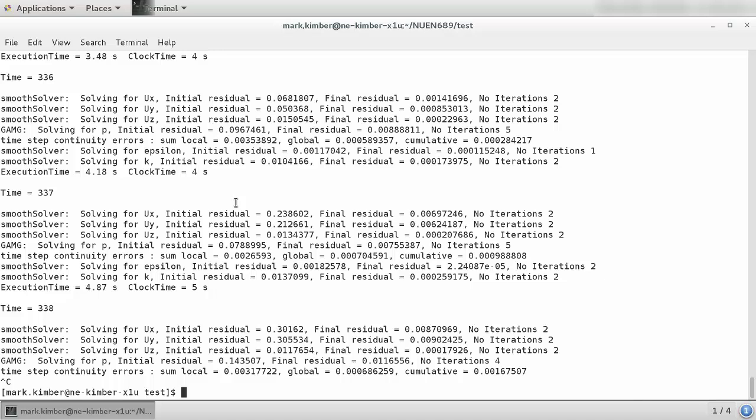So the velocity is obviously a vector. If we were going to build a profile of kinetic energy, then that's going to be non-uniform scalar instead of vector. And if we are going to build Reynolds stresses in there, then it's going to be non-uniform symmetric tensor instead of scalar and vector. So you can go back to any of the R files that we created, and you can take a look at the format of those. Okay, so this concludes the tutorial for non-uniform profile, and thank you.